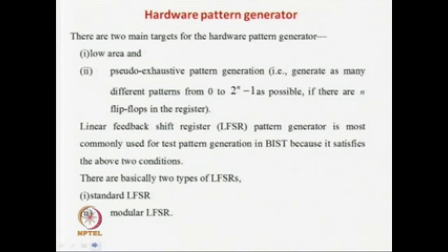Now, there are two major parts of your circuit here. One is your BIST test pattern generator and the other is the response compactor. The compactor is a digital circuit which you have already learned in a digital course. The BIST controller is nothing but a controller circuit; based on requirements you have to generate some signals. It can be easily designed using digital circuit fundamentals and Karnaugh map or Quine-McCluskey optimization. So, only two important parts we have to learn in the testing module are the test pattern generator, that is random test pattern generation, and the response compactor and aliasing. These are the only two modules which we will see; the others you can recollect by going back to your digital circuit fundamentals.